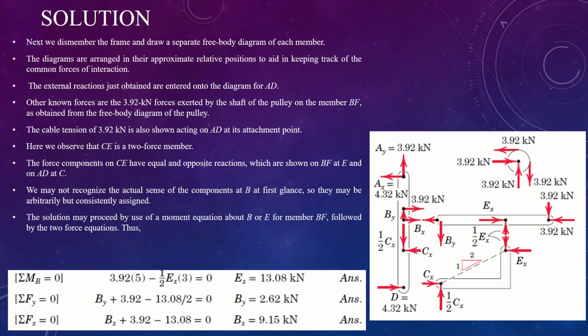So the first thing is we have separated the roller right here. We know the tension D is acting downwards, and this is the rope going over the roller, and then the pin joint is going to face the same kind of reaction forces, opposite to this force and opposite to this force. So the roller has been isolated. The same forces are going to act on this pin joint, which is going to act on the member, and the member is going to act opposite of these two reactions right here, and then this rim is going to have a corresponding reaction phenomenon.